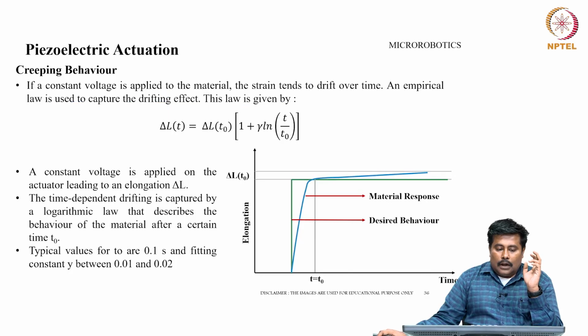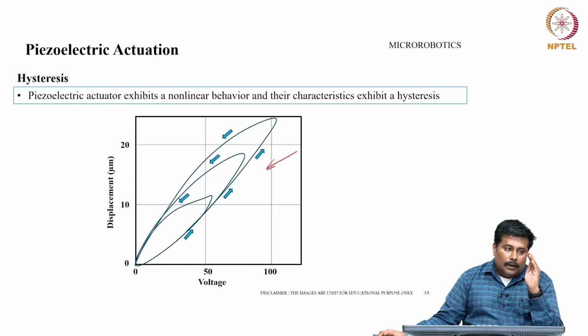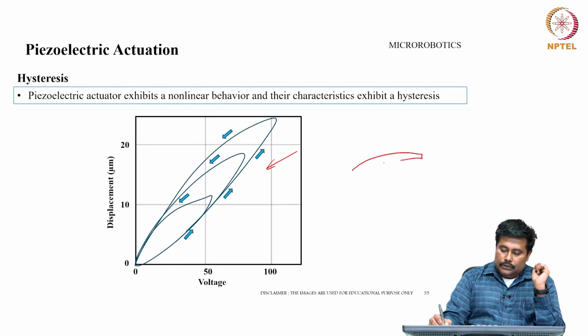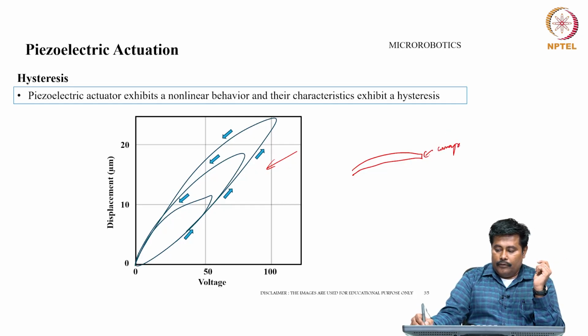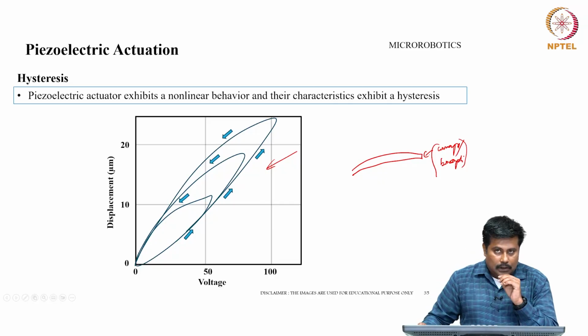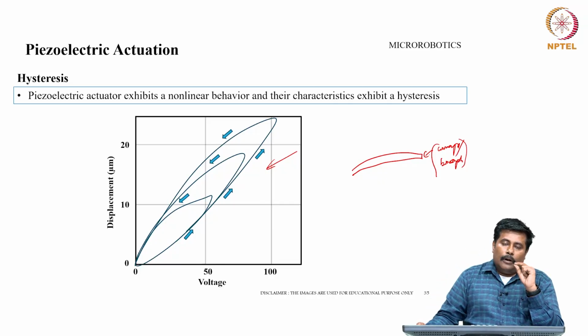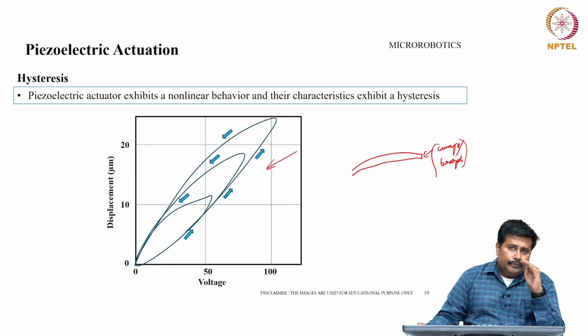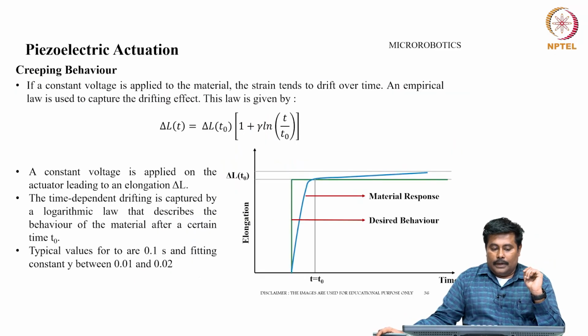So, in order to overcome this, one of the important things people do is add a kind of supporting layer, like the unimorph and bimorph concepts we had discussed. These unimorphs and bimorphs are well integrated with the piezoelectric structures, so that the hysteresis can be considerably reduced and overcome, and the structures can be used functionally for different applications.